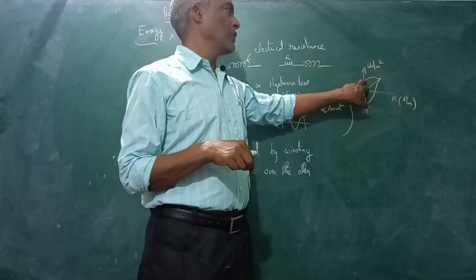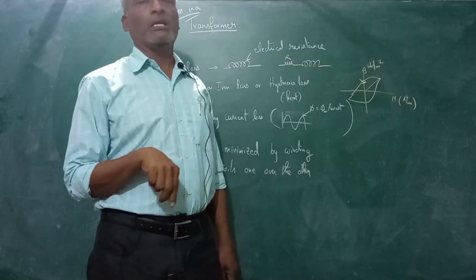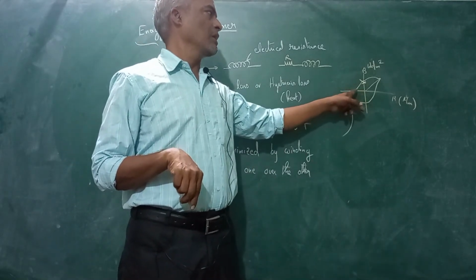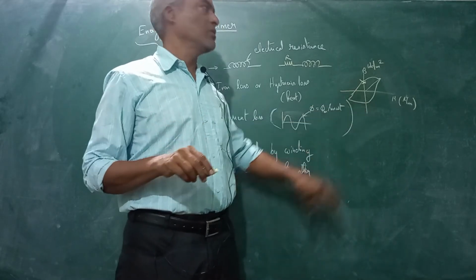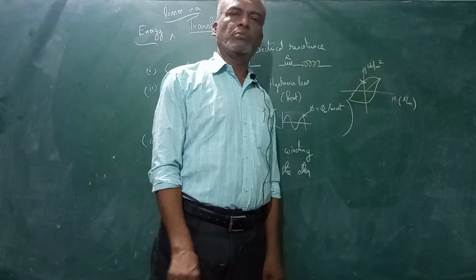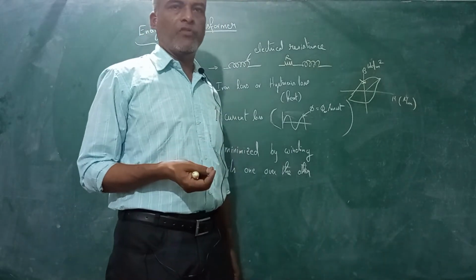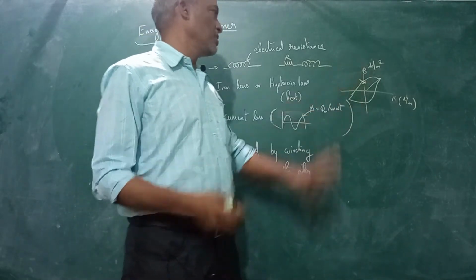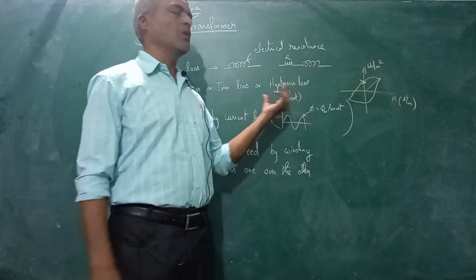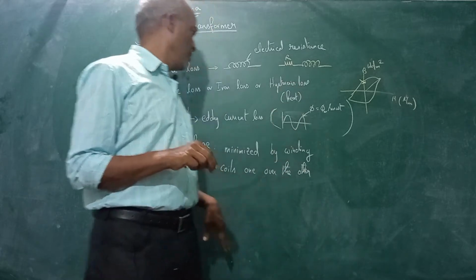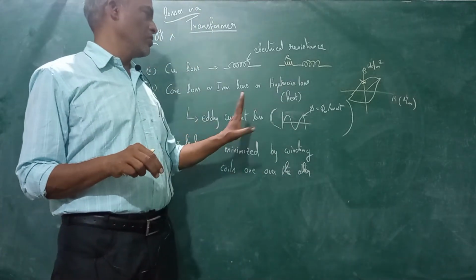In the same magnetic property, when you supply a negative current at this point, it gets erased. So this hysteresis concept is being used in magnetic tape for recording. So this is hysteresis loss. The hysteresis loss happens in the core, and it is transformed into heat. And we told about eddy current loss also.